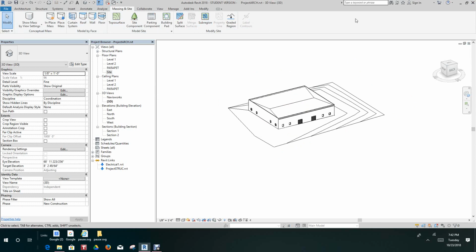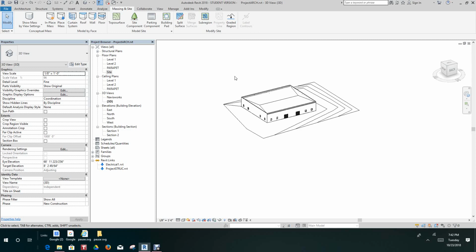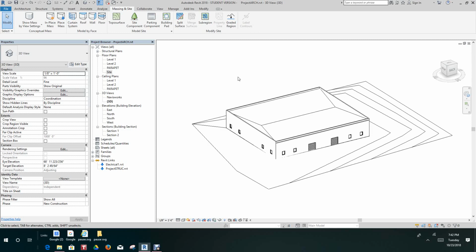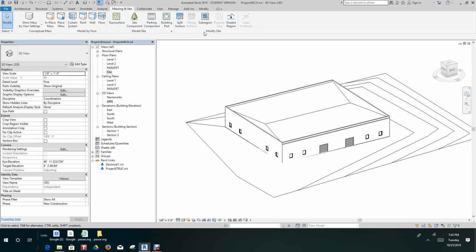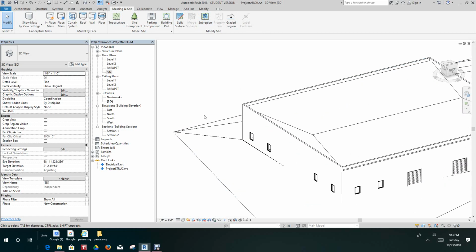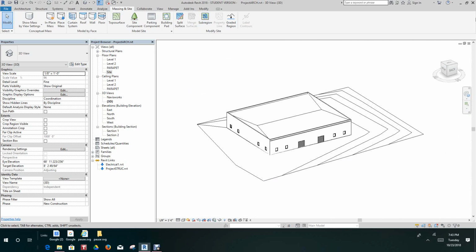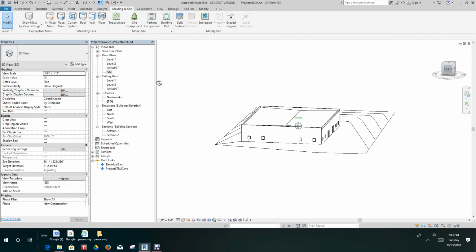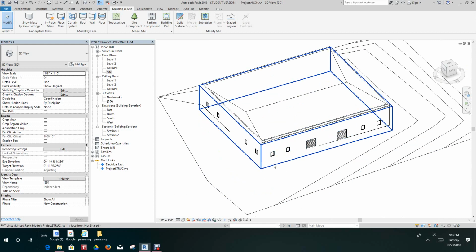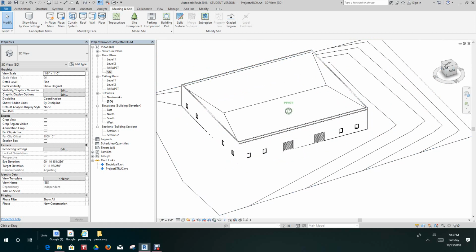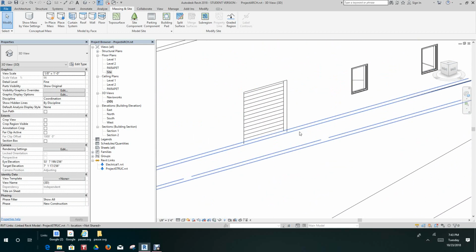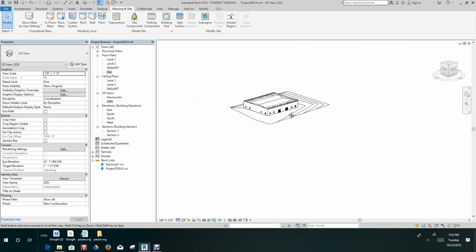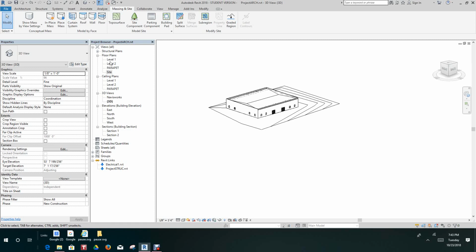So now what we need to do here is, one other thing I want to let you know is also for these surfaces, you can import a CAD or a survey file in here and do this. We're doing this manually. You can take an AutoCAD electronic survey and link it in or import it in. Maybe later on we'll try that, but we need an electronic survey first. I think this looks okay because what we want to do is clear this area. So now we have our topo surface in here. And let's go back to our site.